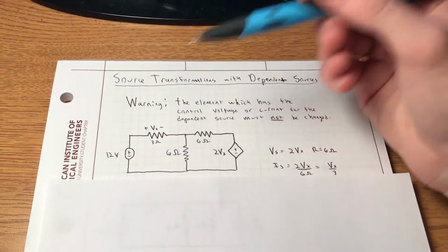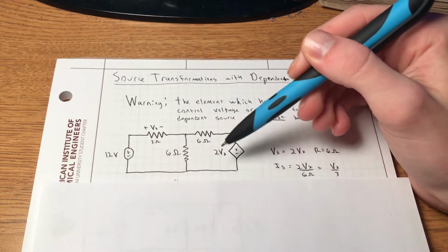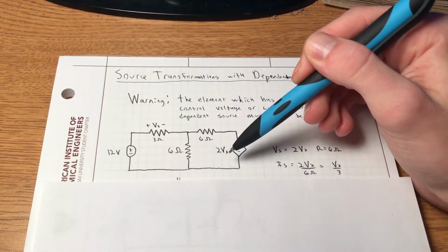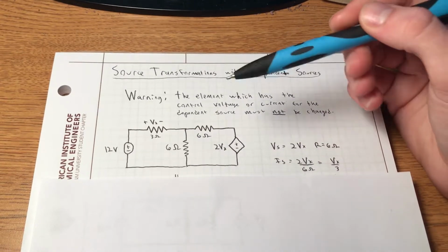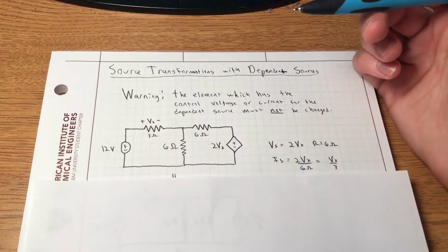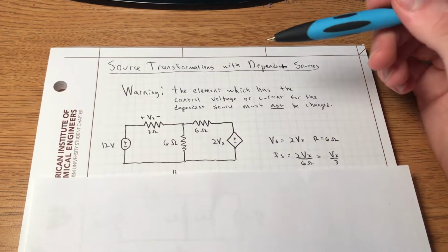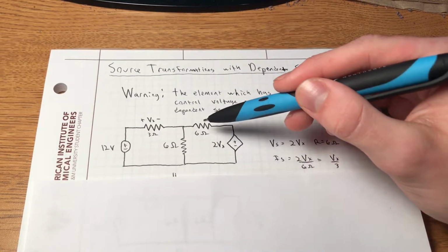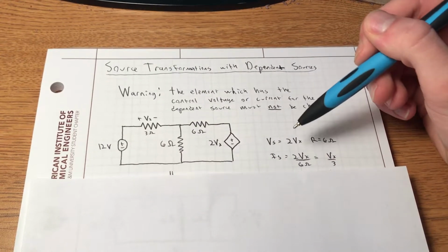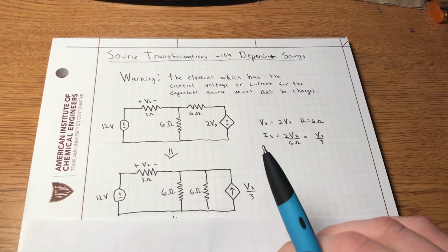So let's look at the following circuit. Here, that element with the control voltage is right here, this Vx. We have a voltage-dependent voltage source over here that's dependent on that Vx. Right? So let's examine this circuit and find the voltage across Vx. Now there's multiple ways to do this, but one valid and simple way is through source transformations. So we can see here that this resistor is in series with this dependent source. So using the following equations here, we could find that this transformation is valid.